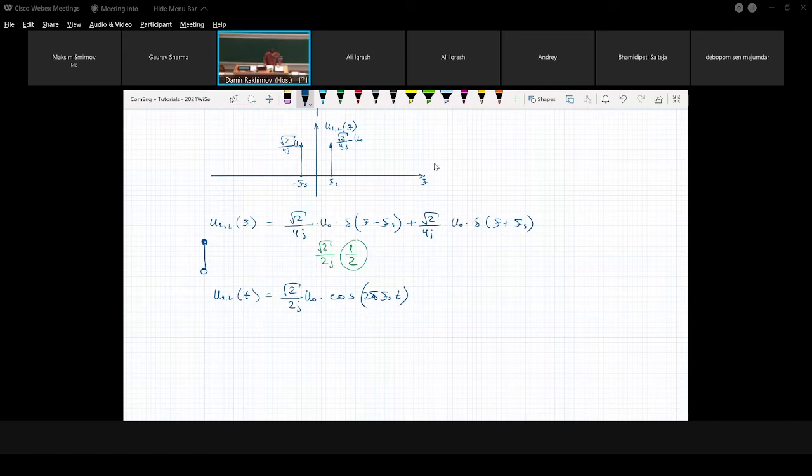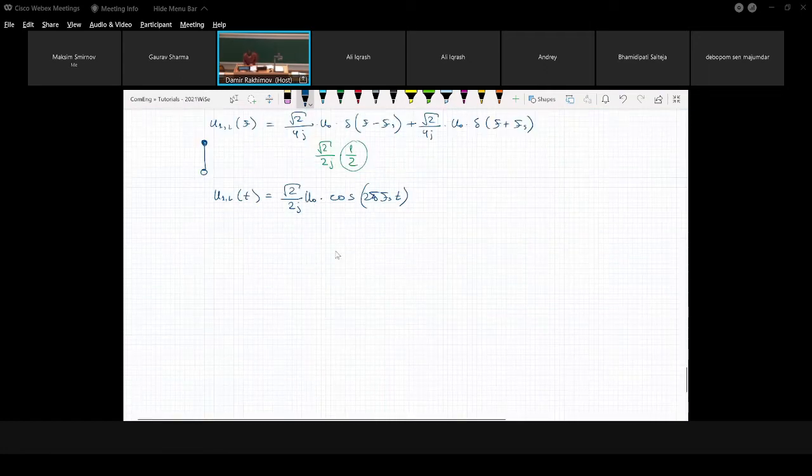Draw the impulse response gL of t and the transfer function GL of f in the equivalent low pass range. Okay. Now we come to the discussion about the filter itself. Everything we did before was about signals, but now we discuss the filter. Originally, we have the filter given as a transfer function in the bandpass range. Now we need to understand how to convert it to the equivalent low pass range. The procedure is actually even easier than for the signal itself.